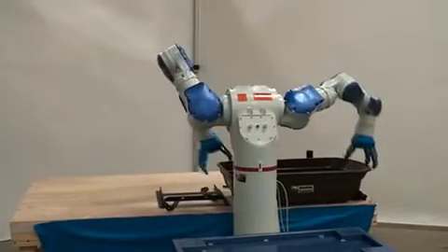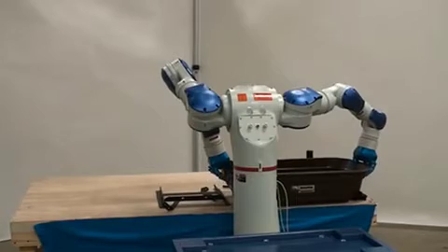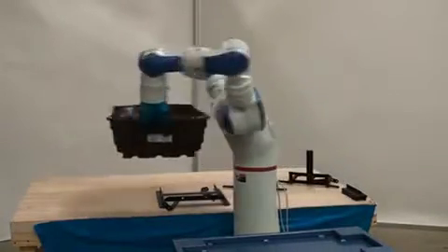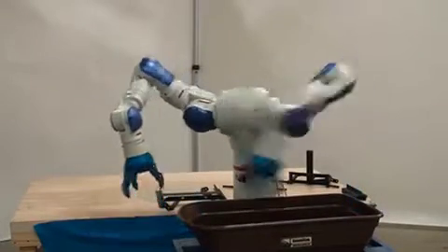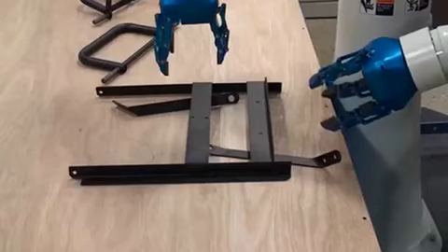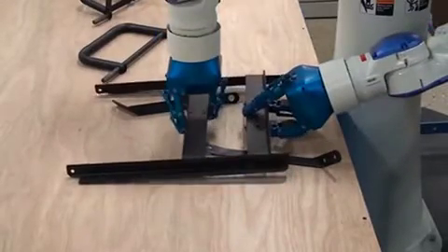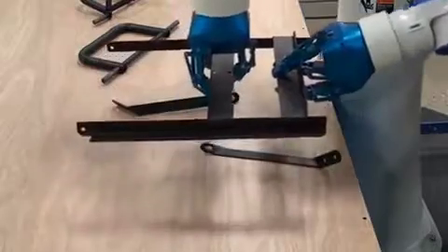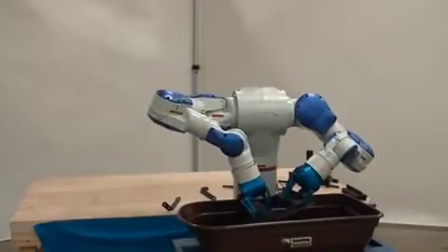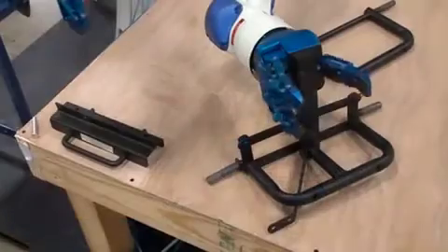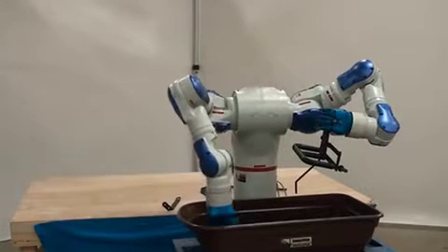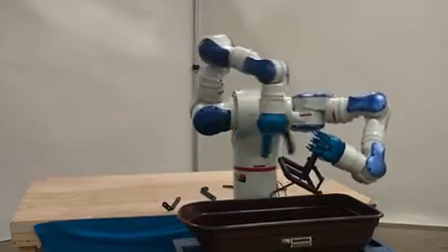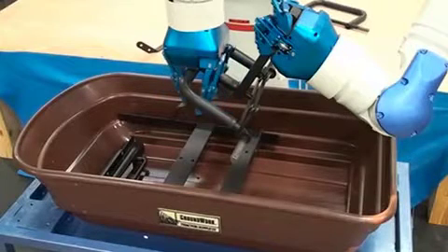This is what's called an under-actuated grasper. In this case, there are 3 fingers, and those 3 fingers have 4 motors, one for each of the fingers, and a 4th that affects the relationship amongst the fingers. And with this under-actuated grasper, we're able to deal with a host of different geometries, holding a metal component in what would be a typical parallel grasp. These are flexible end effectors to go with flexible manipulators on a human scale.